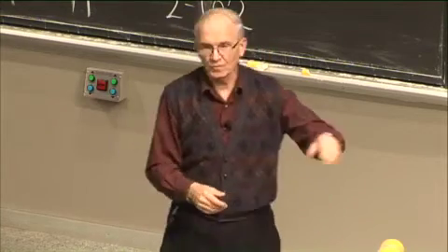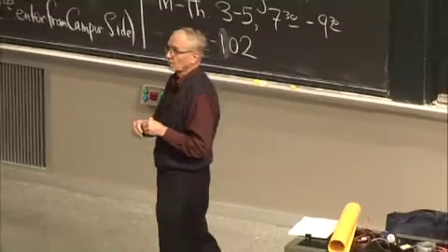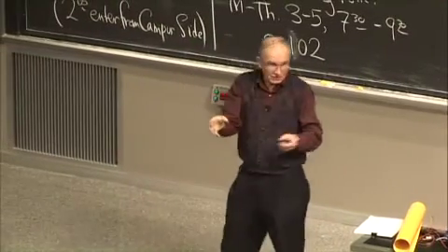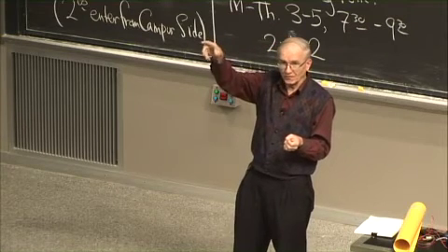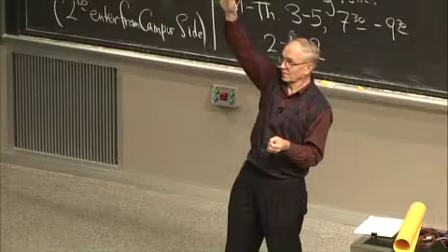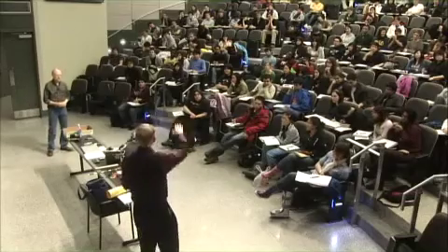And that's how, with the strobe, you determine you've got the right one. You get it at 1900 RPM and you say, I think it's right, but you double it. You put it up at 3800 and see what it looks like. And in this case, you see it up here and then down there. You get a double image.